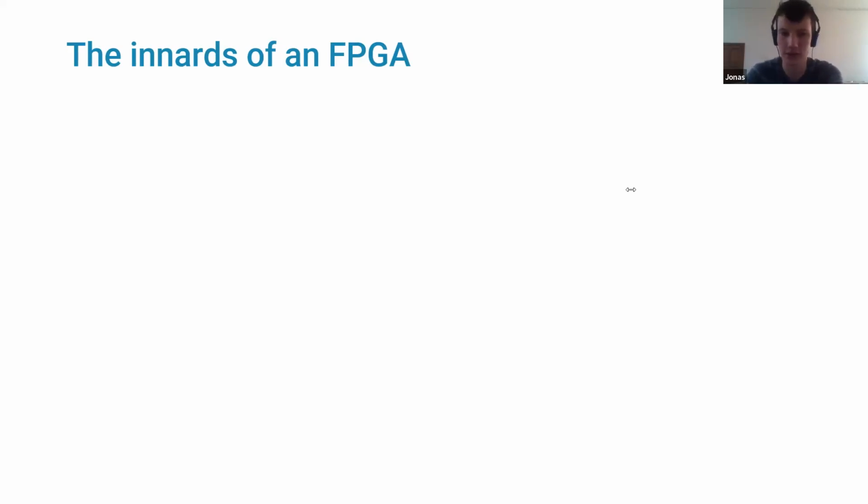And all the things other than LUTs were smaller percentage-wise. BRAMs was like 10%, DSPs was like 6%. So 1/4 of a U280. I did not use custom floor planning because it is small enough. I am running it at 100 megahertz.